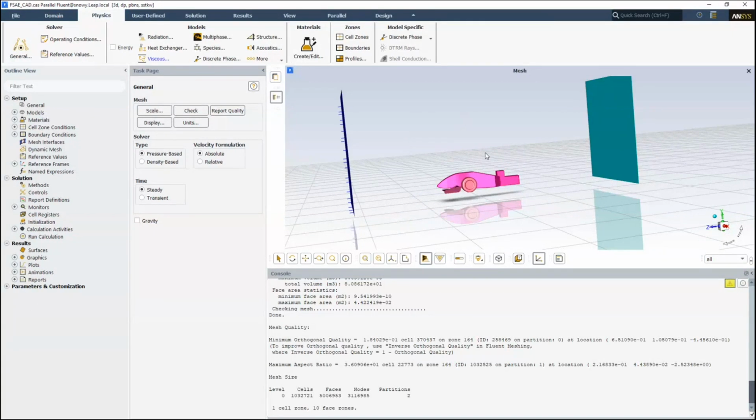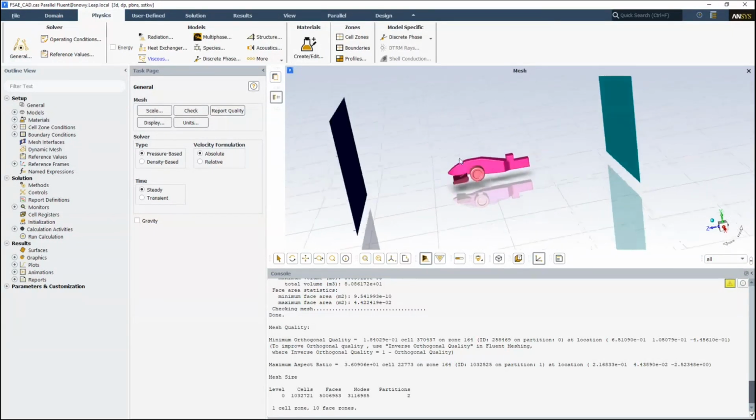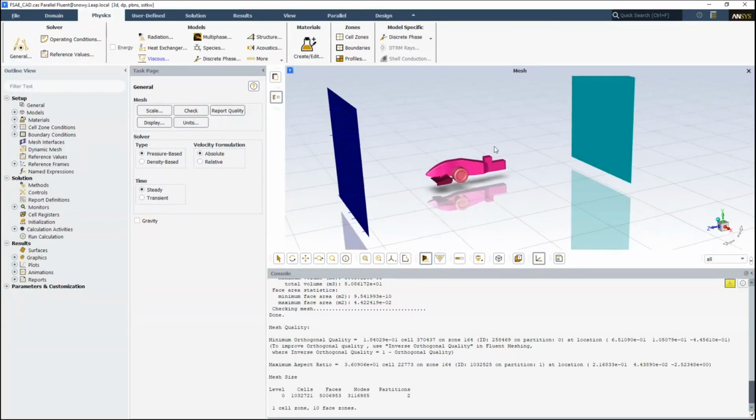So now that we're confident we have a high quality mesh and a relevant sized enclosure, we'll go through some of these other parameters. In our general solver settings, we'll be using the pressure-based solver. That's what we use for most simulations. We can use the density-based solver if we're looking at high Mach number flows, so supersonic flows, Mach numbers above 3, but generally we're using the pressure-based.